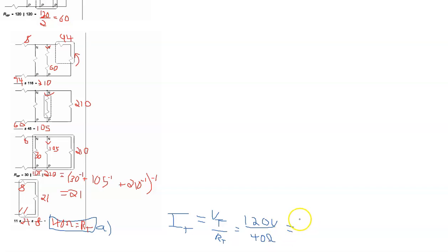And so remember, the reason why we have to go through all this is that this circuit starts off with 2 resistors, an 8 ohm and 11 ohm in series with the source, and a bunch of other resistors connected on the right side. And none of those resistors has 120 volts across them.